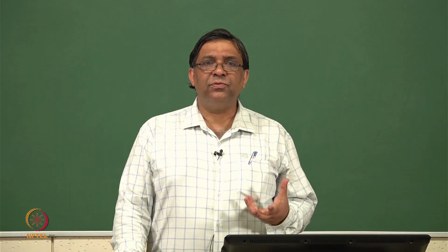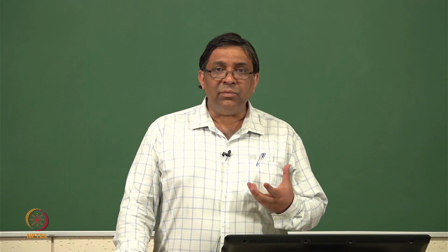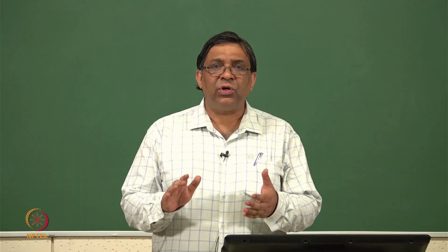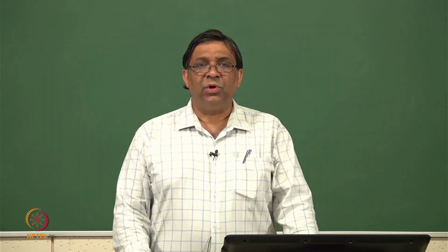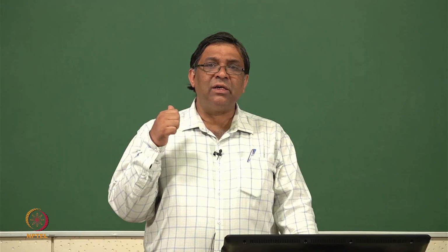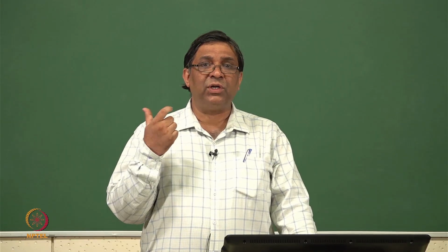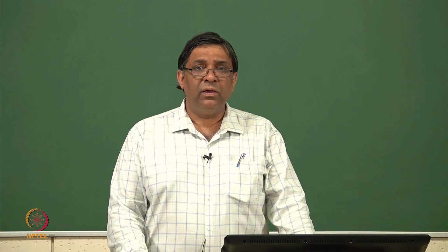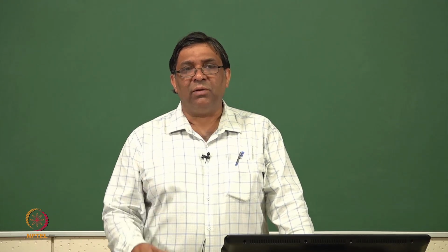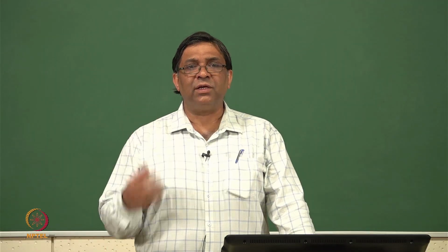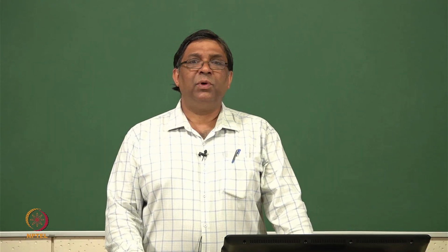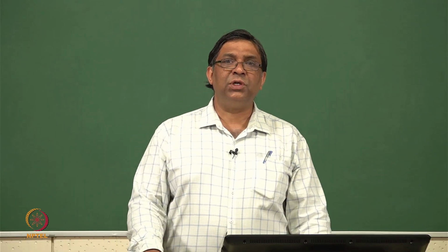And in the last part of my previous lecture, I mentioned one optical layer which is extremely important, which is required in solar cell, because when light falls on a solar cell, there is a tendency that light gets reflected back, and particularly silicon is a good reflector. But the idea is that we have to absorb more and more light in the active medium, and if light gets reflected back, then this light is not being used. So what is the solution for that?